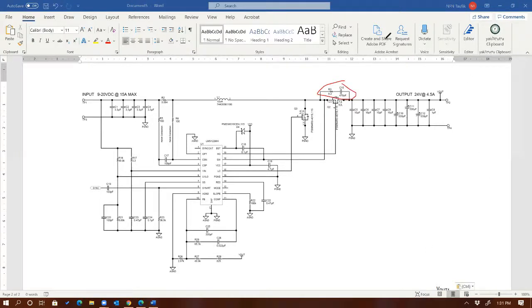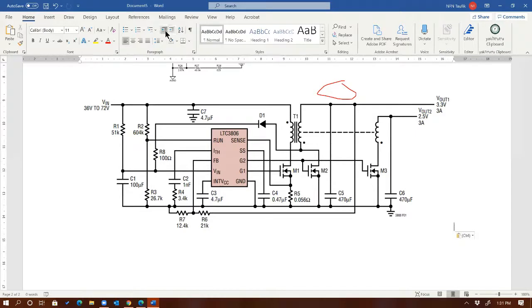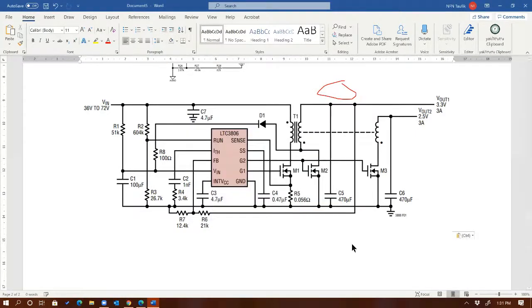All right, and I think one more thing, and then we can adjourn right there. It's not only for non-isolated, but also for isolated converters. Can you tell me what topology this is? Flyback, right? Flyback, very good. So you can see the diode of the flyback is replaced by a MOSFET right there. So keep in mind that we also have controllers being used for isolated synchronous topology.